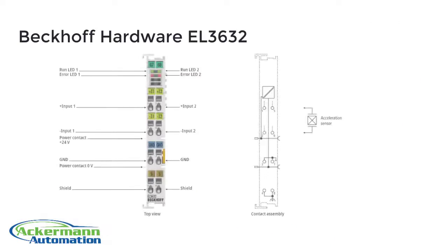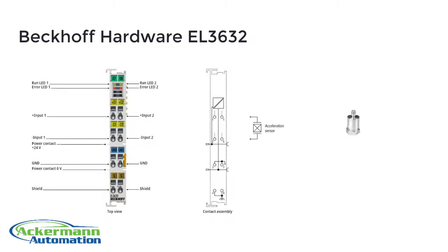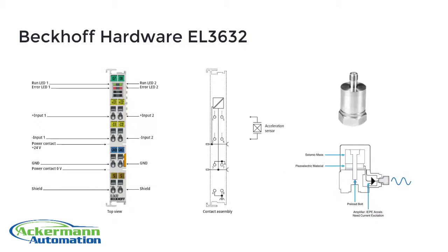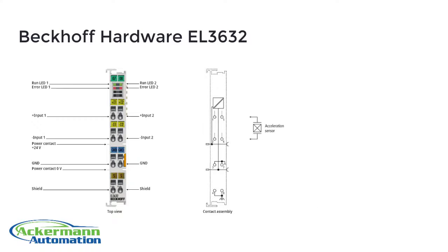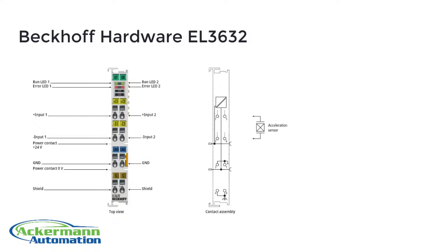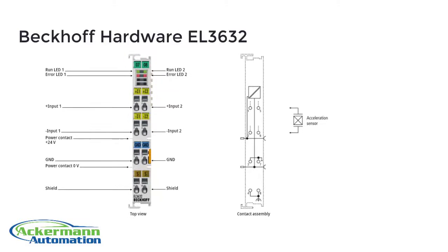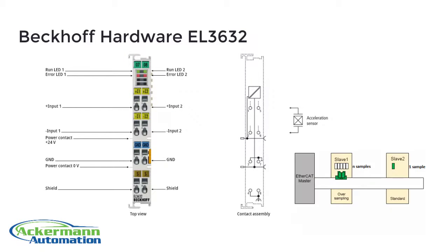The Beckhoff EL3632 terminal connects directly to IEPE sensors, which use piezoelectric effects to measure acceleration, force or pressure. Microphones also apply to the IEPE standard. It has 2 channels, which can be sampled with up to 50,000 samples per second per channel. The sampled data is made available over the EtherCAT bus using oversampling technology.